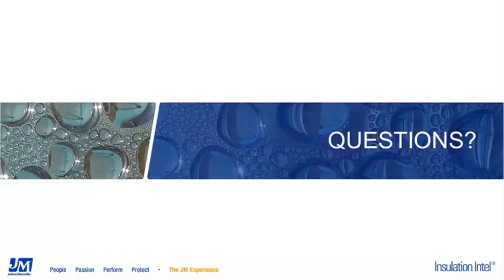All right, thanks. Elaborate a little bit. I would say that's probably correct. I will say that there's not a lot of PVC used outside, but we want to distinguish one thing here. Outside, the way Meredith was saying it and the way I mean it is sunlight exposure. If it's like in the parking garage where it's completely protected from the sunlight, but it's technically outdoors, I think PVC would be fine. In sunlight exposure, you have to be a little more concerned with the things that Meredith is saying.